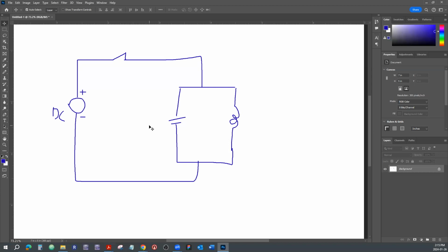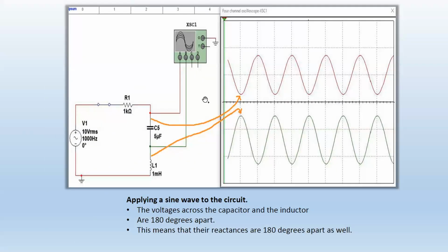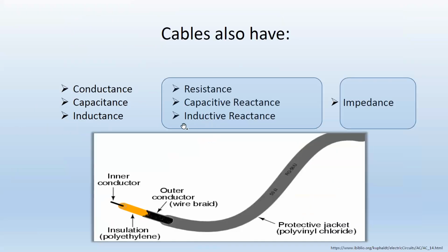So, I should probably connect this thing in Multisim, maybe using real parts, and that's going to be fun to show. So in parallel, you get a tank circuit. And it's the opposite of the series, because in series it just conducts, no problem, that frequency, 50 hertz for example, and this one here is going to block the 50 hertz frequency, and that 50 hertz frequency is going to start oscillating within this tank circuit, right? There we go. So, all right, that was the last slide here.